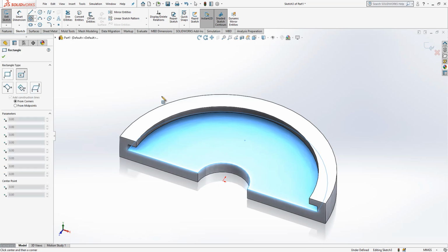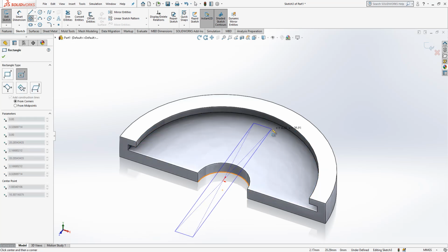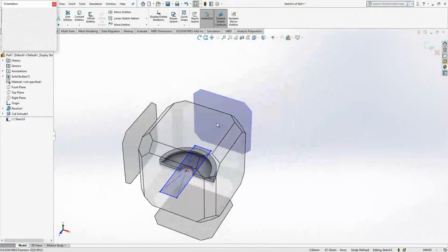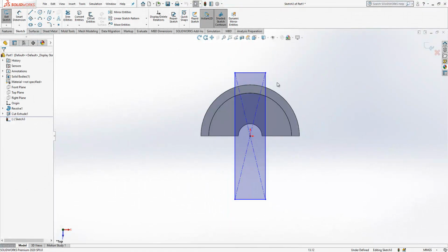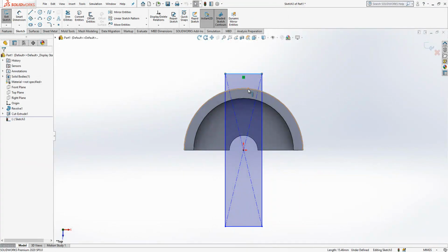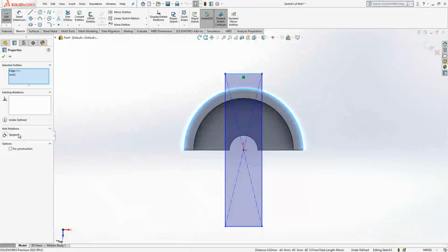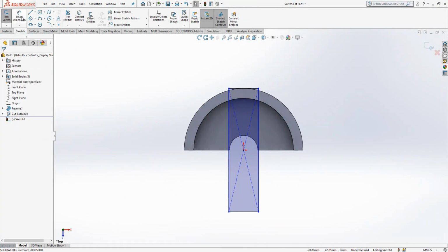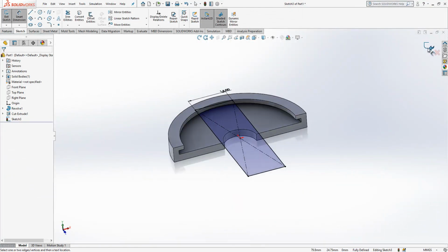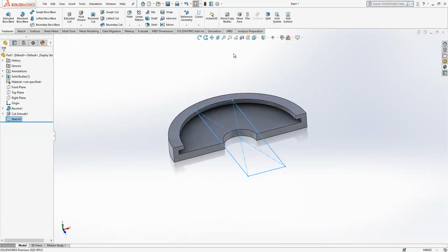Now I'm going to pick a rectangle. This is a center rectangle. Again, center rectangle on the origin and looks like something like this. And then I look from projection. Control is pressed. This edge selected. Control still pressed. And then I say tangent. Here I will give a 14. Yes, it looks good. We can continue.